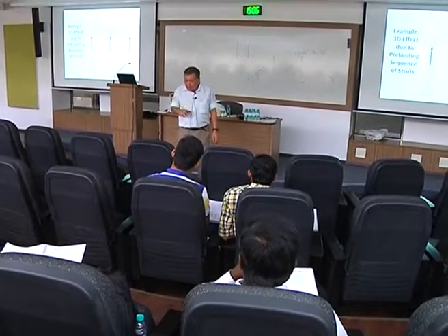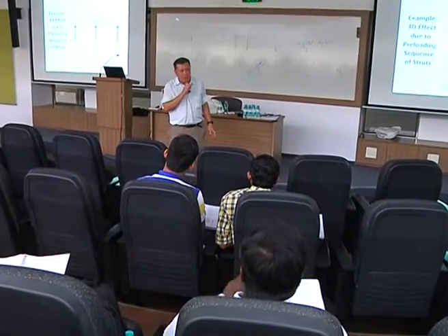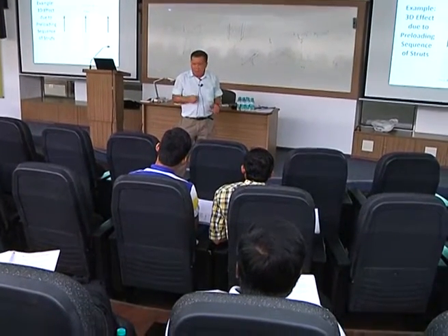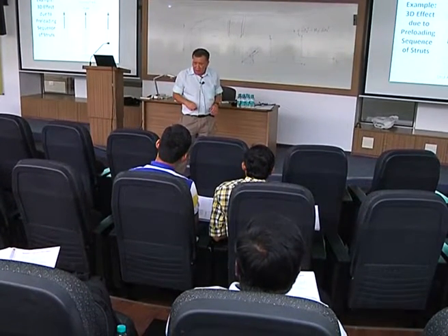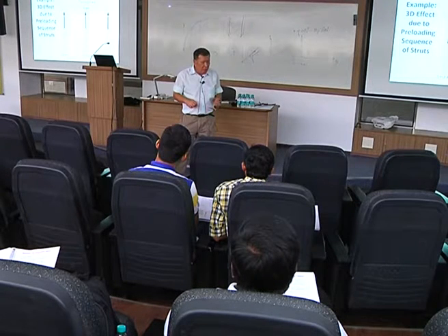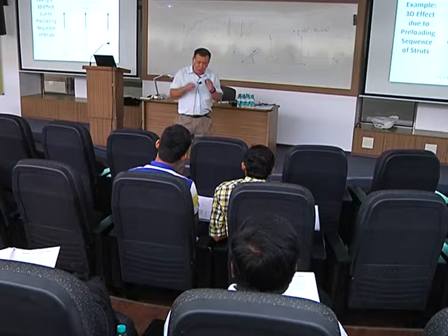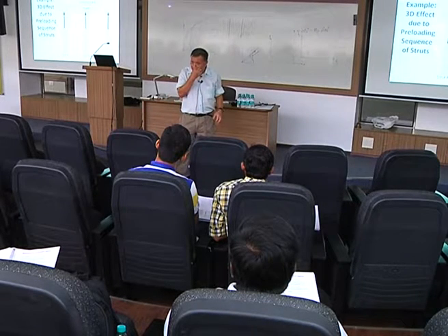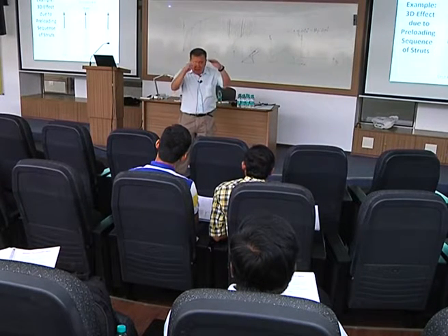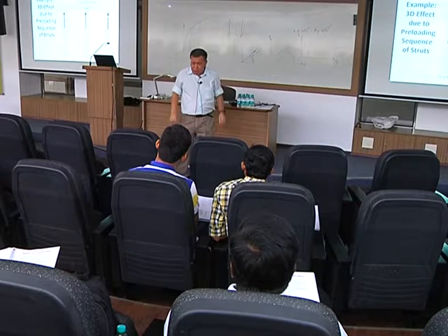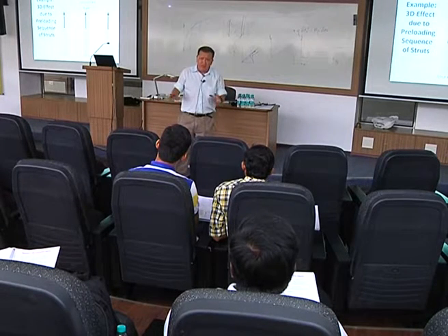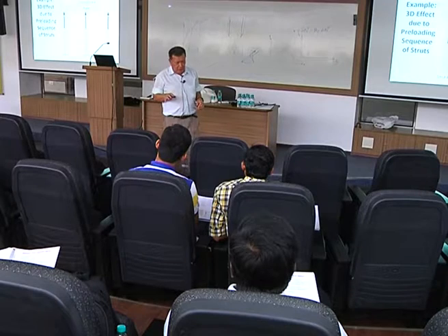And he told me this, he said, I don't understand why we seem to be losing a lot of preload on the Nicoll Highway. He said, we are only getting 30% of our preloaded value remaining. After a while, even in the early struts, in the upper level struts, they already saw it. They couldn't understand why this is the case.